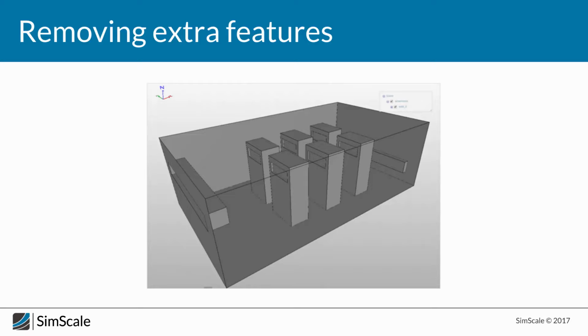If this is not done, if we are really sticking to making all these little details, first of all, we'll experience bad mesh quality around these elements, since the solver or the mesher will try to resolve the element itself. By doing that, it might, for example, ignore it, since it's very small, but very often it will still leave a bump or a little discontinuity of the mesh at the place where it was located. Later, during the analysis, this kind of irregularity of the mesh might cause problems for convergence or even running the whole thing.